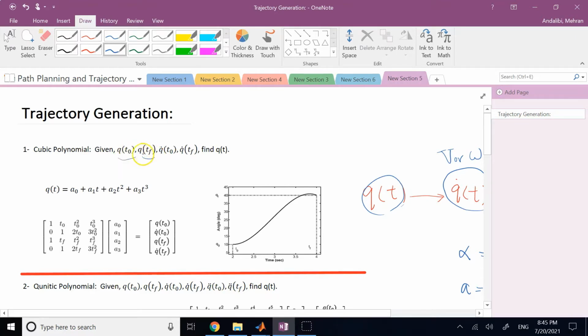And the timing I have is from 0 to 2 seconds. So in 2 seconds, your joint has to rotate 400 radians, which is on average 200 radians per second. And if you multiply that by 60 over 2 pi, you can convert it into RPM.